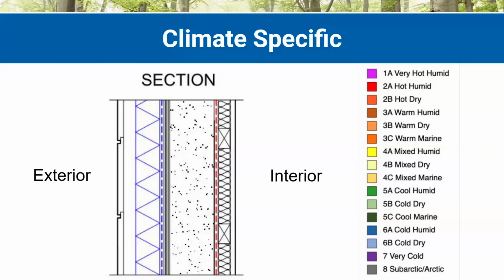But once we're in these more northern climates, these cool or cold climates, our vapor drive is mainly from the interior going out. So that Intello membrane becomes very key, and we want to have a very high vapor permeability on the exterior, such as the Solitex Mento membrane, whether that's over plywood or if they're going sheathingless, it would be the Mento Plus that would have the netting built in. So we're slightly tweaking things based on climate zone. We're maybe changing that exterior vapor permeability some.